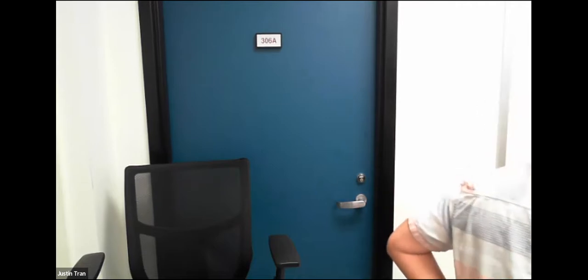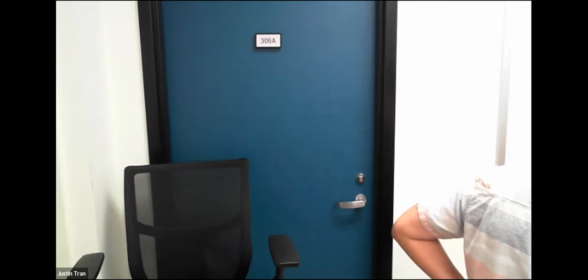I just want to make sure I analyze it properly, because I did exactly what you did. I just put a boundary condition for fixed support inside the hole, so it stayed still, and then I applied force to the face up here. Of course, the force acts on all of that, but I just wanted to ask if there was a way to analyze everything as a whole, so that it could be somewhat more realistic.